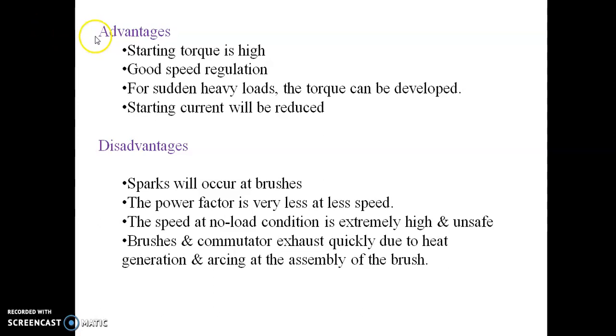Now let us discuss in detail the advantages and disadvantages of the repulsion motor. The advantages are that the starting torque is high, it has good speed regulation, and even for heavy unexpected loads, sufficient torque can be developed.